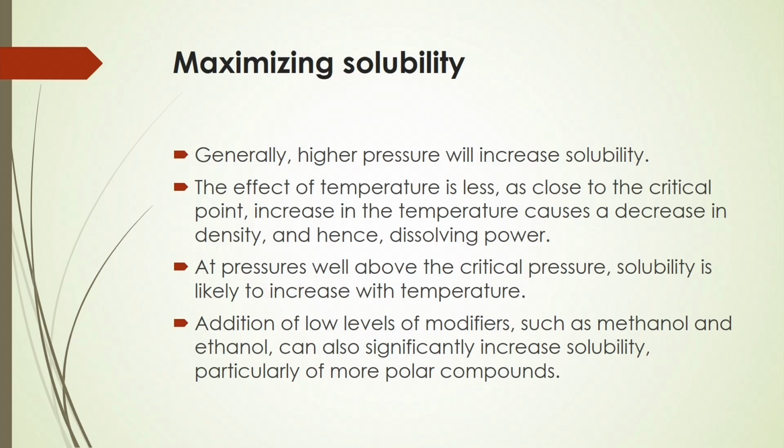So, you have to consider how to increase the solvation power, and how temperature will affect the solvation power at the critical condition. The effect of temperature is less close to the critical point, since an increase in temperature causes a decrease in density, and hence in dissolving power.